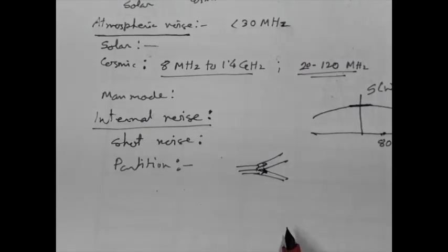It is thus expected that the diode would be less noisy than a transistor, and it is for this reason that the input of microwave receivers are often directly taken to the diode mixers. The spectrum of partition noise is almost flat. Active three-terminal components in which the control terminal draws less current are less noisy, quite obvious.